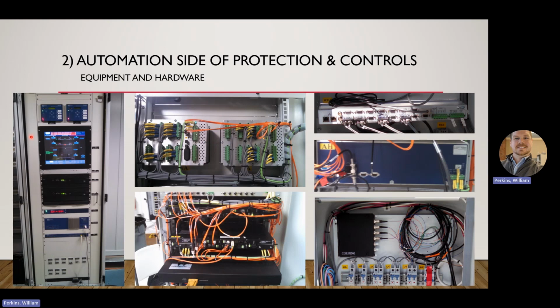interface to fiber. And on the left here, we've got a pretty good overview of a SCADA cabinet, in which we can see some 2411s at the top, which are typically taking in your hardwired inputs and possibly providing outputs. Below that is your HMI for the operator to interface with the station.